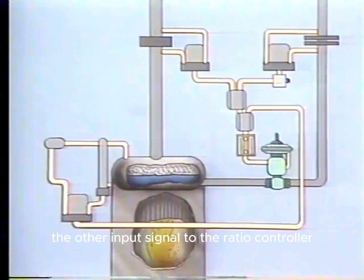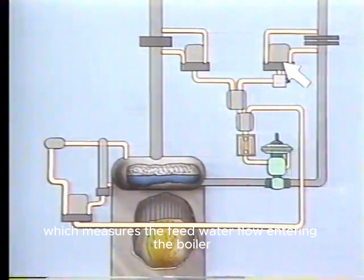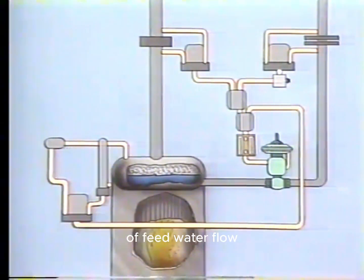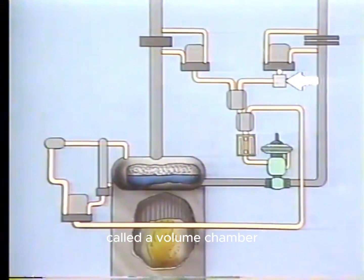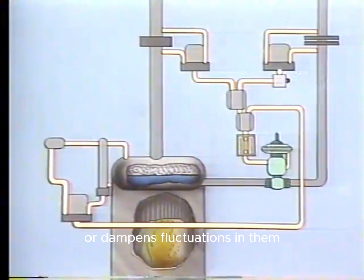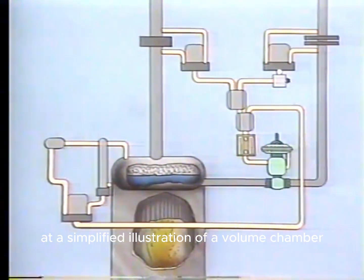The other input signal to the ratio controller comes from this transmitter, which measures the feed water flow entering the boiler. The transmitter produces an output signal that represents the value of feed water flow. The transmitter's output signal is sent to this device, called a volume chamber. A volume chamber delays pneumatic signals or dampens fluctuations in them. We can see how it does this by looking at a simplified illustration of a volume chamber.